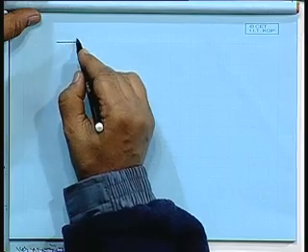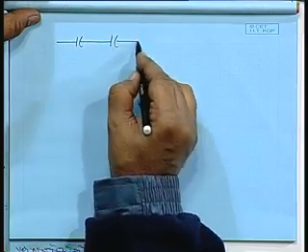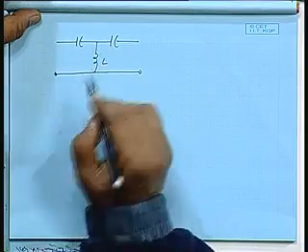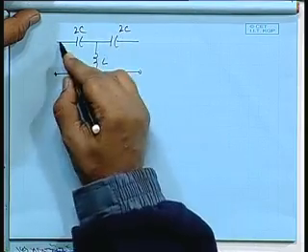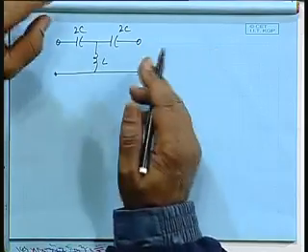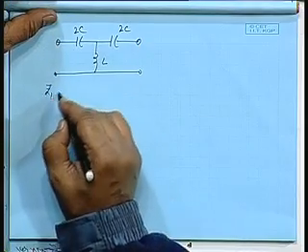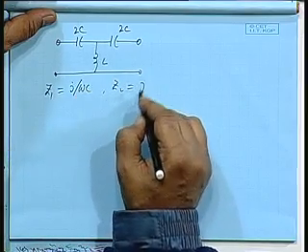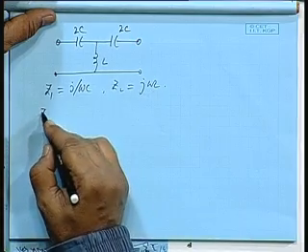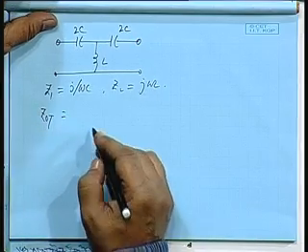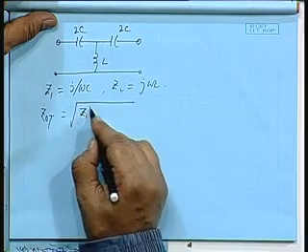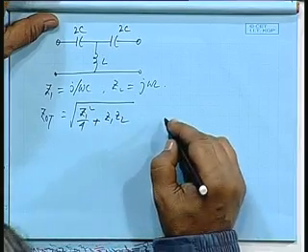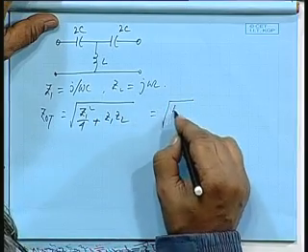Now, instead of inductance, if you have capacitance in series and inductance in parallel, this arrangement, then what do you get? Z1 and Z2 have interchanged their element types. So Z1 becomes 1 by j omega C, and Z2 becomes j omega L. So Z O T, I will just write the expression for the T network, which is the root of Z1 squared by 4 plus Z1 Z2. That gives me root over L by C